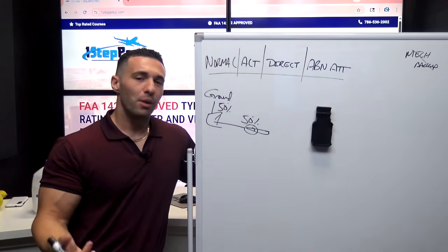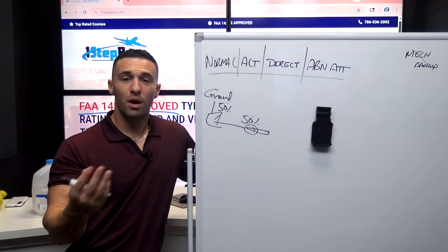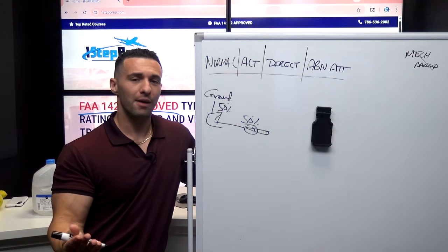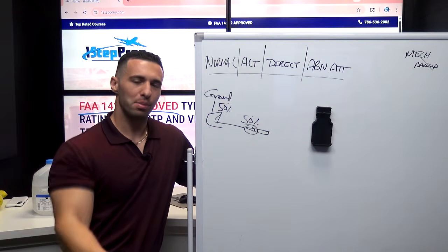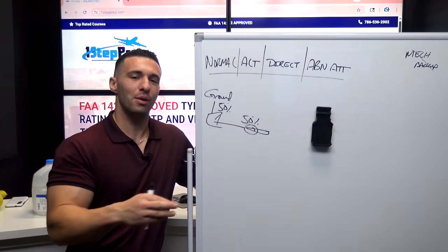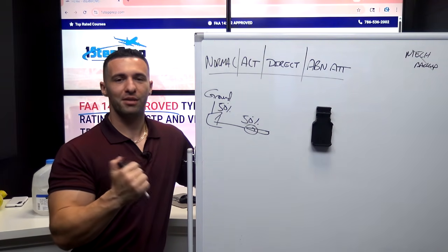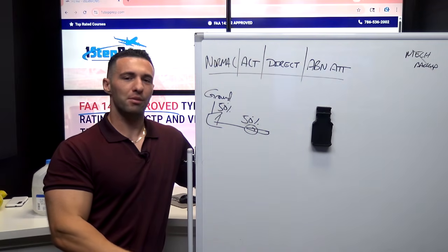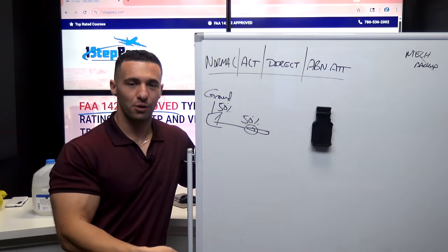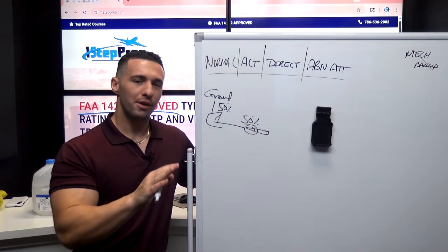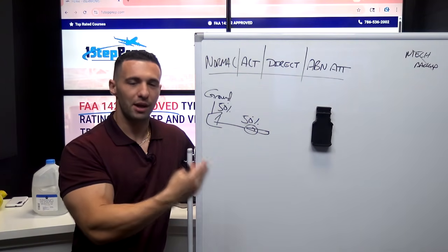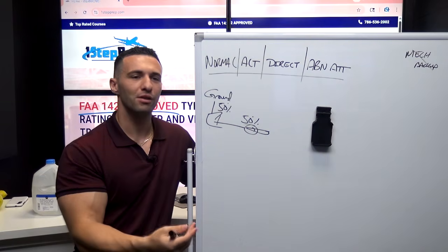The reason it's that way really is two things. One, because I've got to rotate the aircraft off the runway, and I can't pull more than 1 G on a two-dimensional playing field, which is on planet Earth, right? So the ELAC doesn't understand positive G's on the ground because it can't pull any more than 1 G on the ground. And so in order to rotate off and give me a nose-up elevator deflection, I need a direct communication between side stick and elevator, right? So that's the first thing.